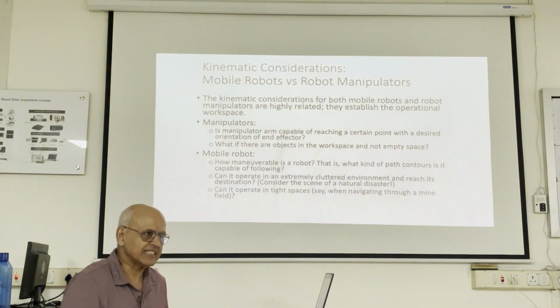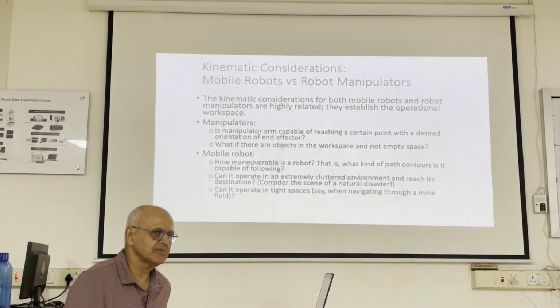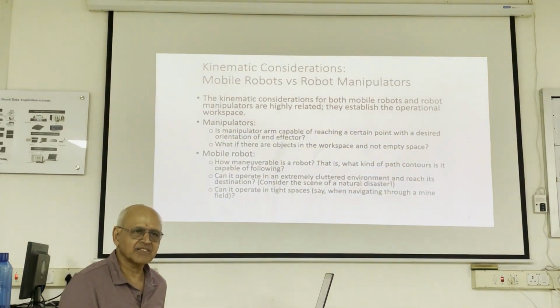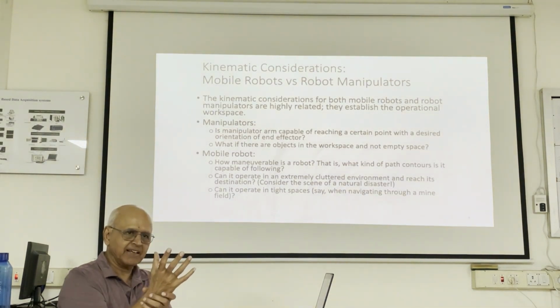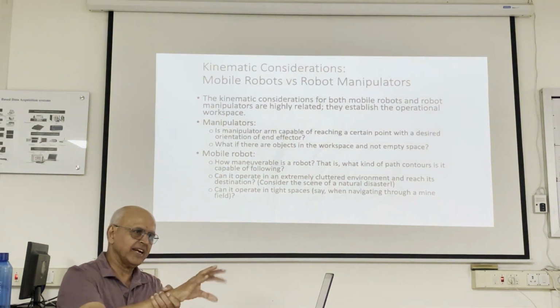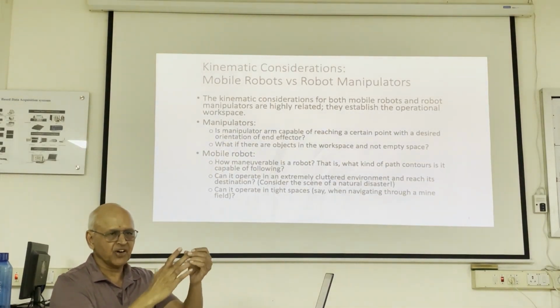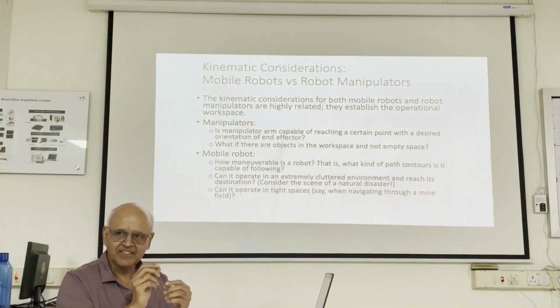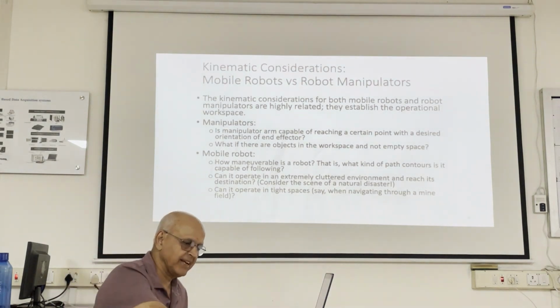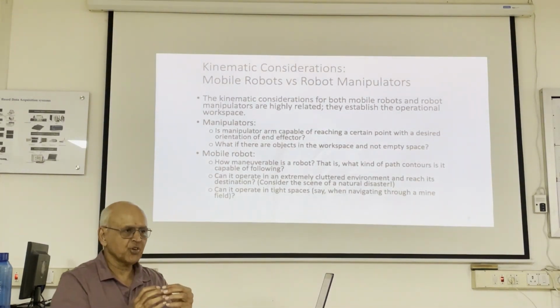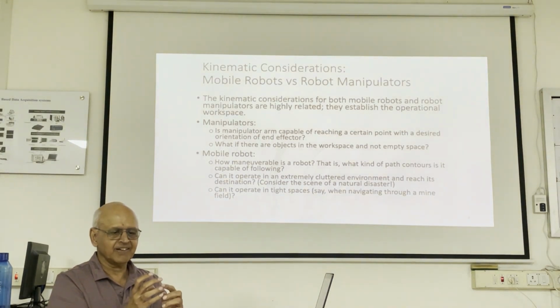So the difference is the base is anchored. Because the base is anchored, it makes certain tasks very easy. And the biggest task is localization. Because the base is anchored, and all these joints, you know the lengths and how much each joint is rotated, then pretty much most of the time it's possible to figure out, we call this the end effector, because ultimately the robot is doing something like welding or picking up something, so you pretty much know where the tips of the robot are.